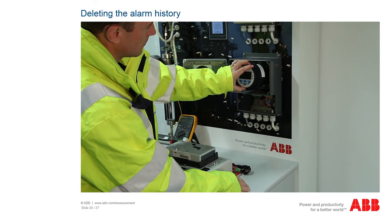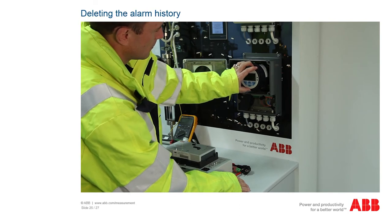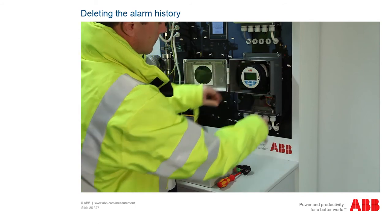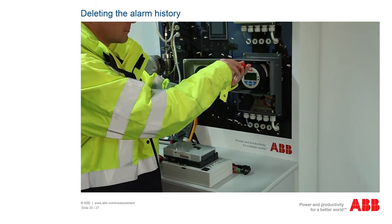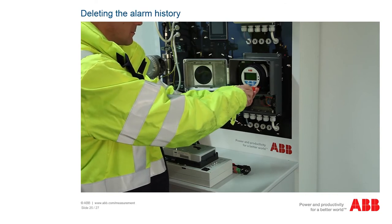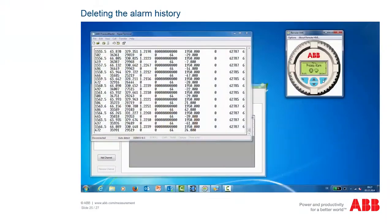If you have not already done so, reinsert the electronics of the flow meter sensor in the control unit and screw the unit closed with the 3 screws. When inserting the flow meter sensor, make sure that you do not bend any of the pins on the connector strips. Now delete the alarm history in the transmitter. You do this in the Process Alarm menu.